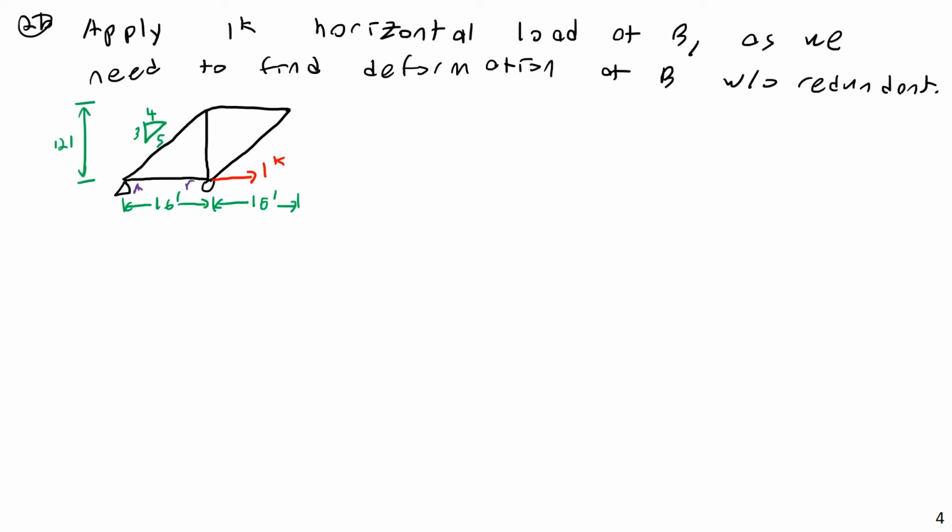And this actually comes to a very simple structural analysis. When you run through the equations here, you will find that the forces in every single member except AB is 0. So our virtual forces here are quite simple. The reactions, AX is going to be equal to negative 1 kip, and both AY and BY are both equal to 0. AY equals BY equals 0 kips.